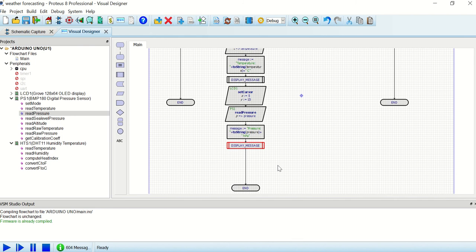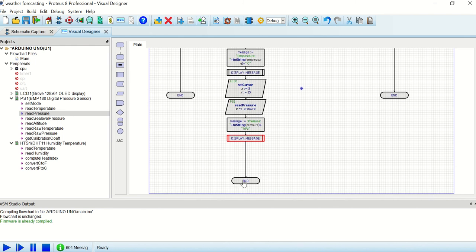Now this is a very small area here, and we cannot initialize the humidity options here. Since we cannot add the humidity here, we can split this overall loop operation. So notice carefully how we can do that. Just place your mouse on the wire and give a right click, and you will get delete or split.